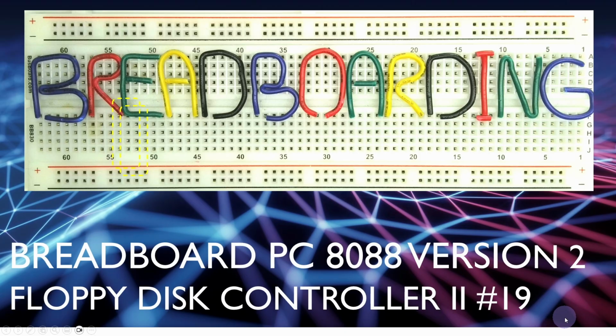So this is video 19 in the Breadboard PC 8088 version 2 series, and this is part 2 of the floppy disk controller. In order to get to the bottom of this, what I thought I'd do is resurrect the Breadboard PC version 1 and put the logic analyzers on the various components and see what correctly operating MS-DOS looks like from the low-level signals.